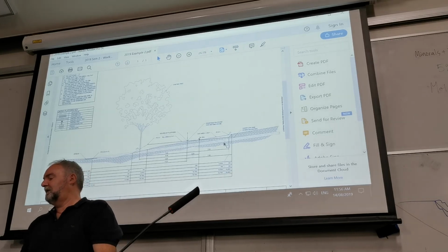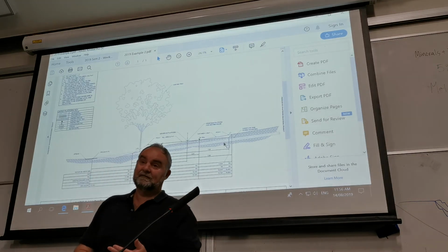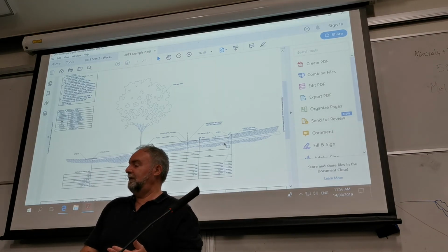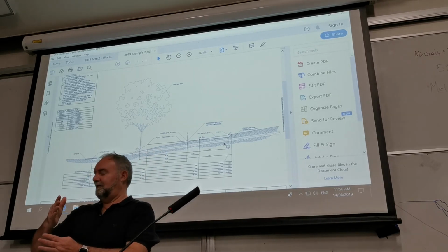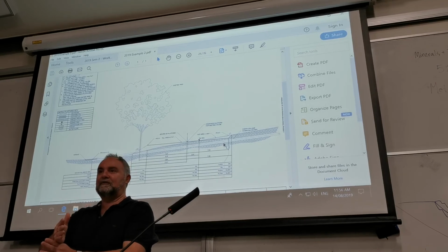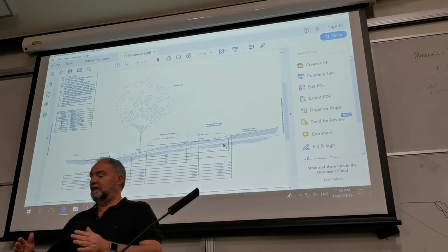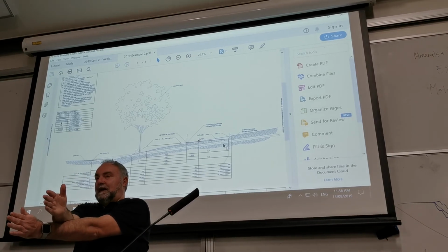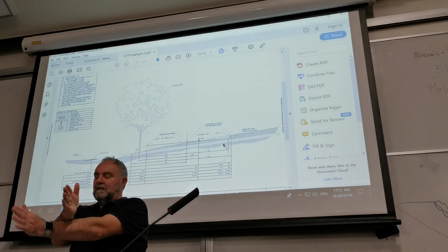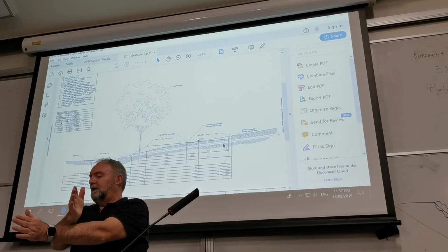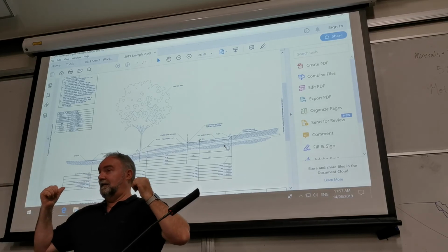On a cross section, we don't show a centre line. Not 100% true. It depends how the pipe crosses the cross section. In this case, the student just drew the line all the way, but the pipe actually crossed over the cross section like that. So the only piece that was solid was the bit where it crossed over, where you cut through the pipe. The bit behind, we're not interested in, so they shouldn't have even shown that.